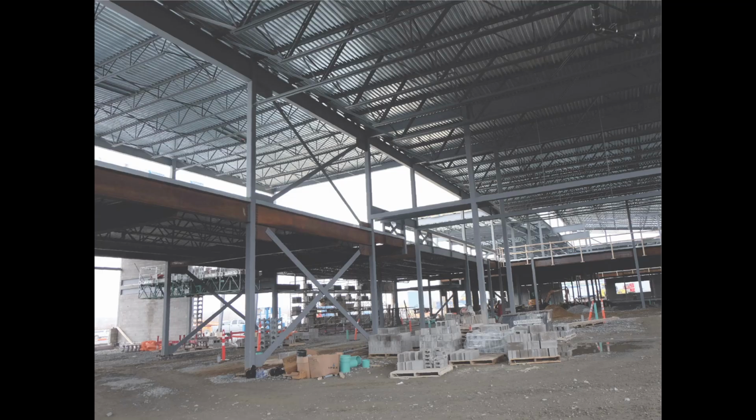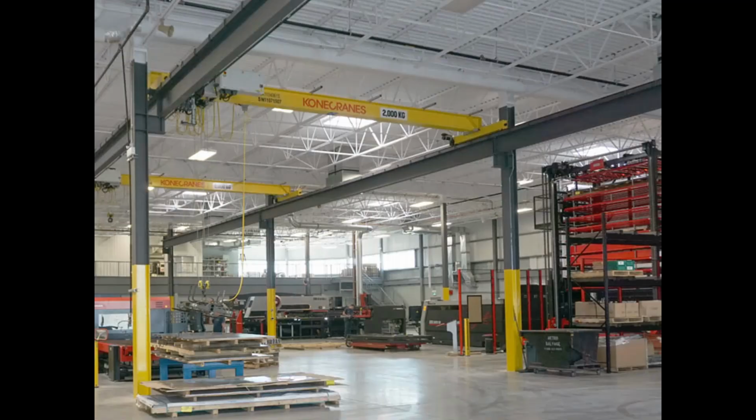Maybe we're looking at a braced frame, and we know that these, which are essentially girders or joists in some sense, depending on which way everything's oriented, this is basically a beam that's responsible for carrying some gravity loads, some shear and bending. But at the same time, when this brace goes into tension and this brace goes into tension, those two tension forces are going to be applying a compression force to the beam in addition to whatever bending's there. So that member is going to see a combination of flexure and compression, and we have to consider the combined effects of those two actions.